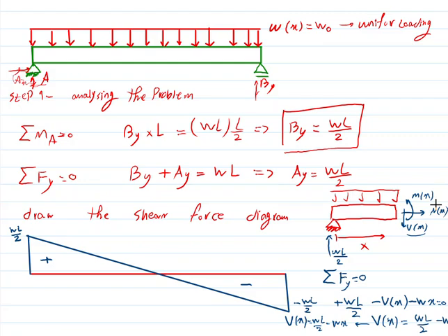The thing is, you think now the loading has the same direction as the shear forces, okay? But think about it. When it has the same direction as the shear forces, it causes the amount of V, or shear force, to decrease, okay?